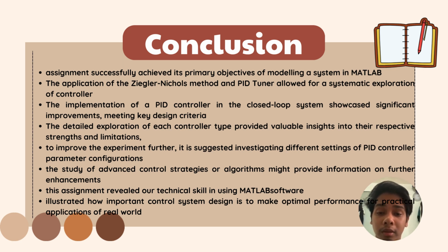open-loop system, and also designing PI and PID controllers for a closed-loop system. The application of the Ziegler-Nichols method and PID tuner allowed for a systematic exploration of controller tuning methodologies. The analysis of the open-loop system revealed its inherent instability, emphasizing the necessity for a robust control strategy. The implementation of a PID controller in the closed-loop system showcased significant improvement, meeting key design criteria such as overshoot, rise time, settling time, and also steady-state error.